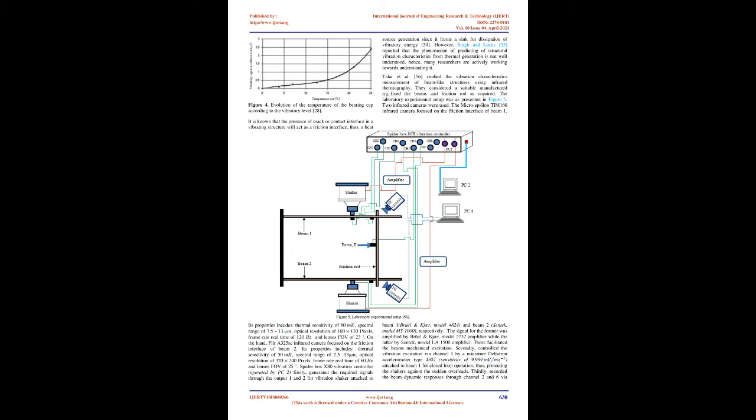Furthermore, because the wind turbine blades are generally manufactured from composite materials, flaws and damage are inevitable during either their assembly or their operational lifetime. For this reason, IRT is predominantly used for the diagnosis of premature failures and for increased reliability in both manufacturing quality control and in-service inspection of structural integrity emanating from the defects [43-48].